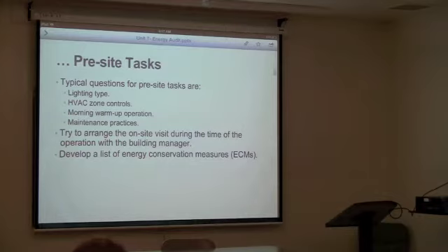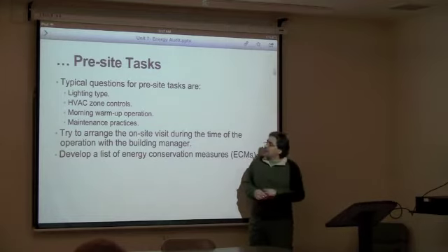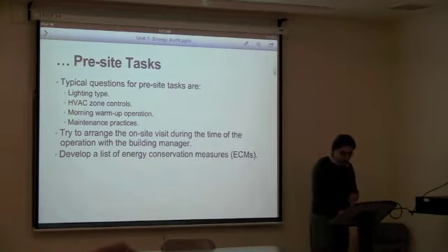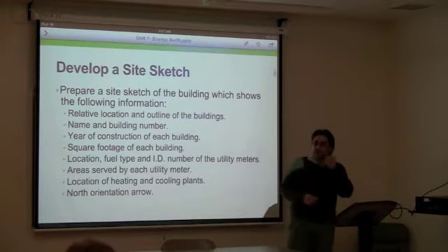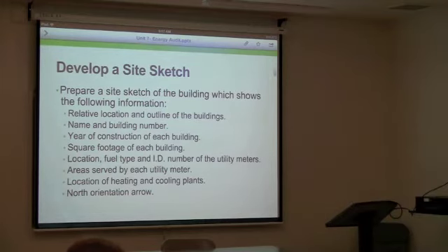So make sure you always know how much of that area is conditioned and what temperature is required to operate for that area. Because if you're dealing with a school, if you're dealing with a hospital, if you're dealing with a shopping mall, they all require different temperatures, right? You cannot always assume 72 degrees Fahrenheit. It doesn't work that way.